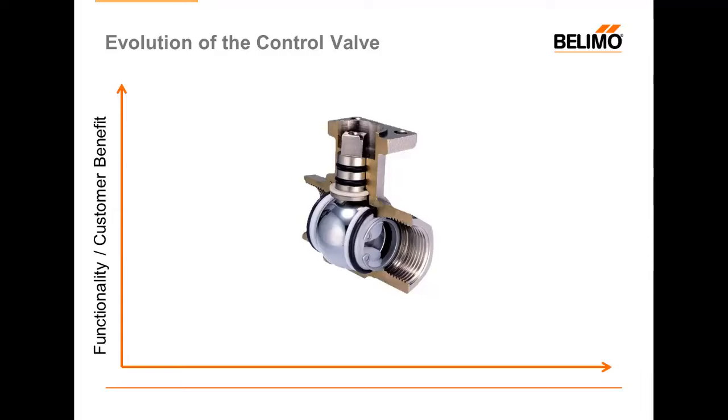The problem with these types of valves is that while the valve may be open the same amount, we don't necessarily get the same amount of flow through that orifice. So if we think about a valve that's halfway open, receiving maybe only a 2 or 3 pound pressure drop, we're going to get a certain amount of flow. But that same valve, in the same half open position that was seeing 8 or 10 pounds of pressure drop, would obviously see a significantly higher amount of water.